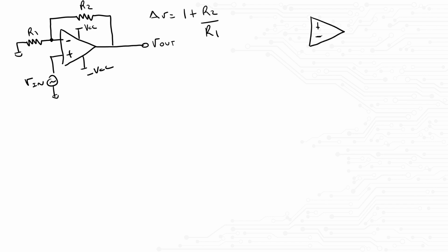Our best bet is to analyze the circuit like we analyze any OpAmp circuit. That is, KCL. So you can start your answer with something like, well, if we flip the polarities of the amplifier, it is not in negative feedback anymore. It actually went into positive feedback. If I remove the resistors for a second to make my life easier, this is just a plain comparator.